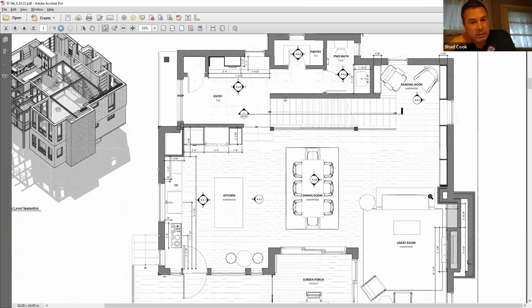We would have to actually penetrate the rim joists of the floor system there to get back in. But I would imagine, no, we'd actually be going through whatever material you are running on the underside of those joists that are cantilevering out there. We would be penetrating that to get into the joist cavity and then laterally over to the office space as we go down along that cantilever. Yeah, I think we'd be below. I think it'd be a little difficult.